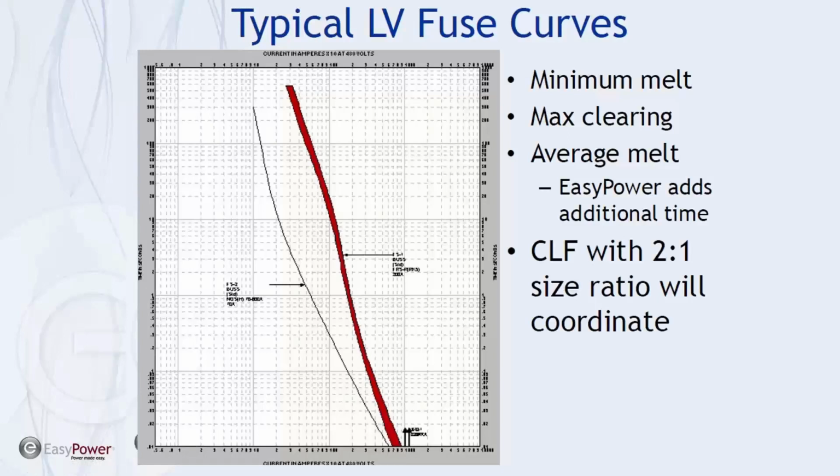Now, as a side note, where this comes into play in arc flash calculations, there can be a time difference such that the longer time gives us a higher incident energy calculation, and that is required or suggested as being a more conservative approach when we're calculating arc flash incident energy.